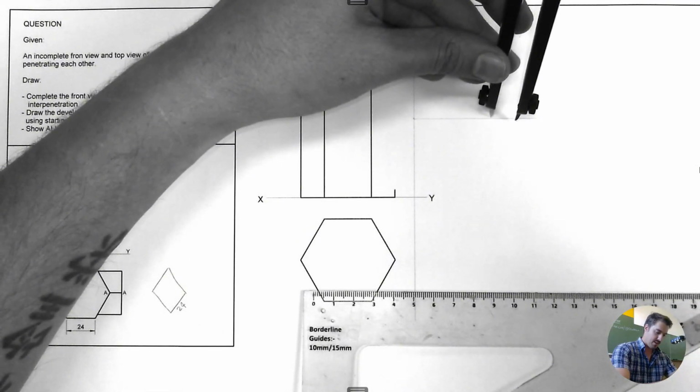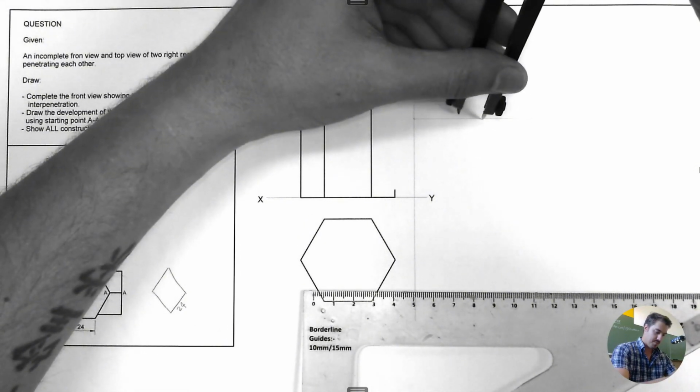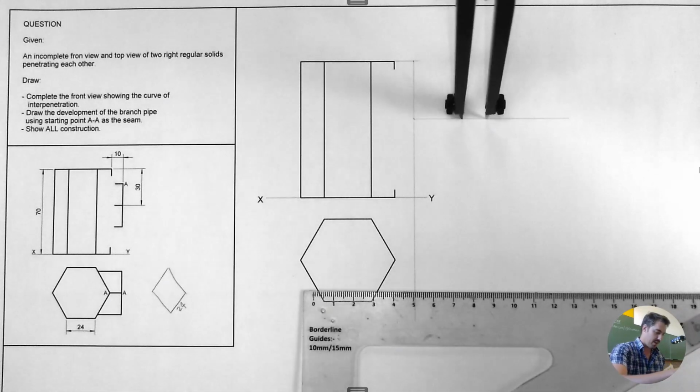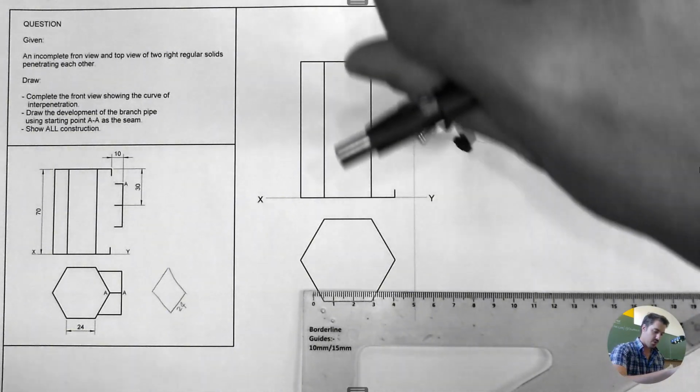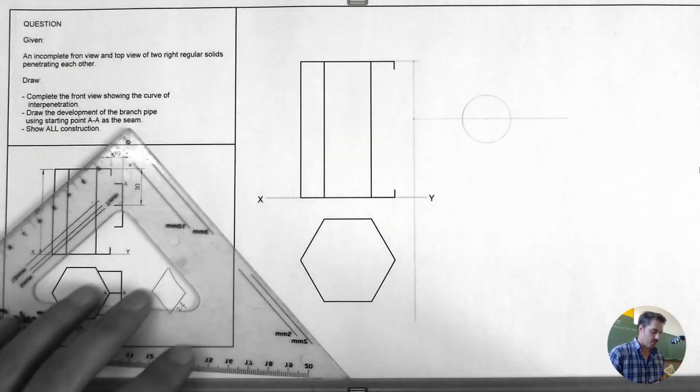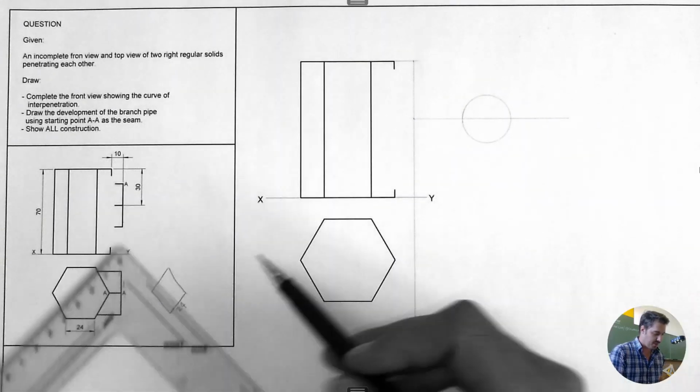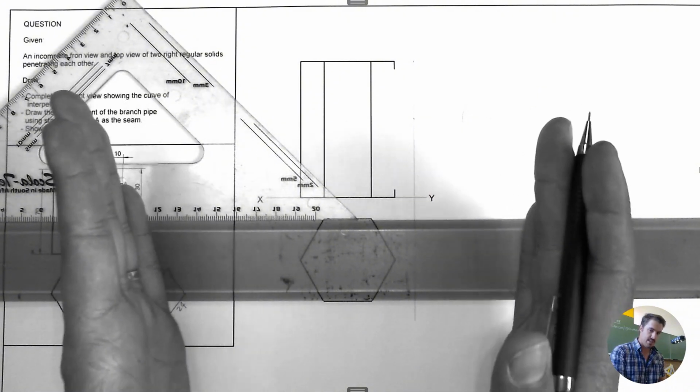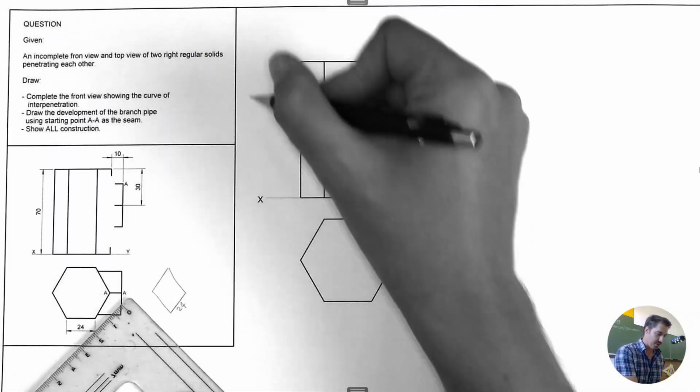And then up here on the middle where the 30 millimeters was, you draw a construction circle that's 12 radius. Now you're going to draw tangents to this on a 45-degree angle, right? Because it's a square. A square is either 90 degrees if it's like this. Let me just draw a quick image.